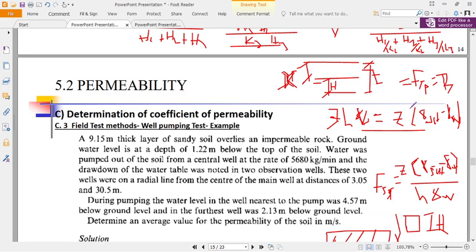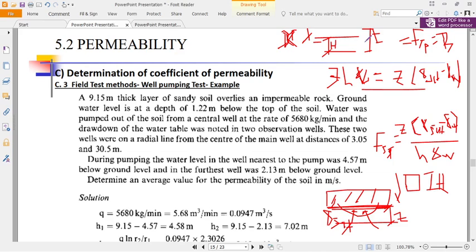So able to determine how much I should excavate to prevent such conditions of piping, or what amount of backfill I should put on a place where piping will occur, due to the construction of a structure which will impose an effective stress. This would be an uplift pressure.